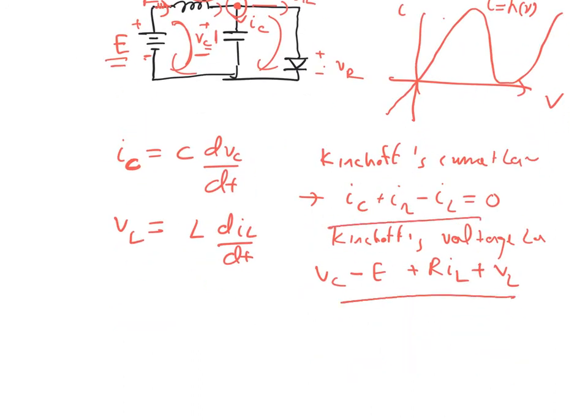We have these two equations now, right? And now we can put, because our states are, in this case, let's choose our states: x1 to be Vc. So the voltage across the capacitor is one state, and the current across the inductor, x2, is IL, is one state. I chose those states because if you know those two, you can define everything else. That's the basic idea. Again, if you remember states, the number of states is the same, but you can always choose different states. Okay, but let's say we choose these states.